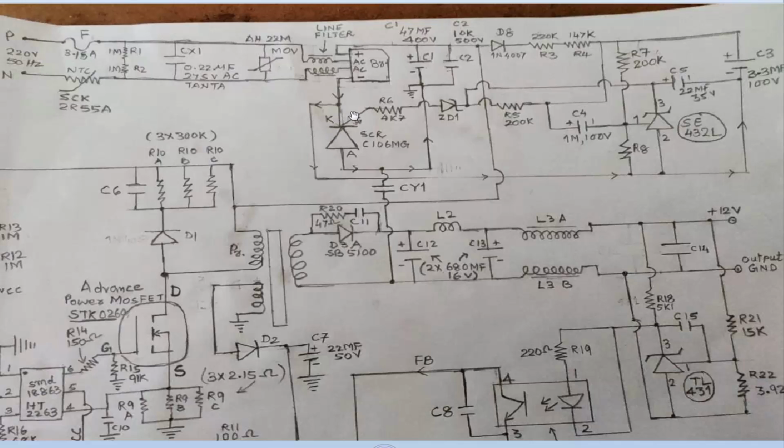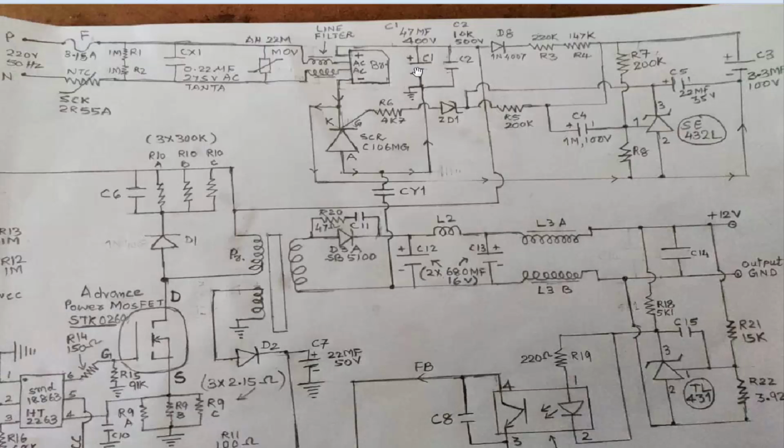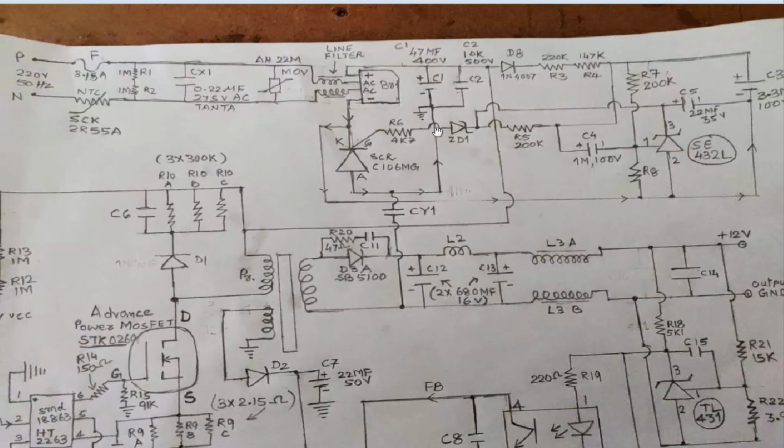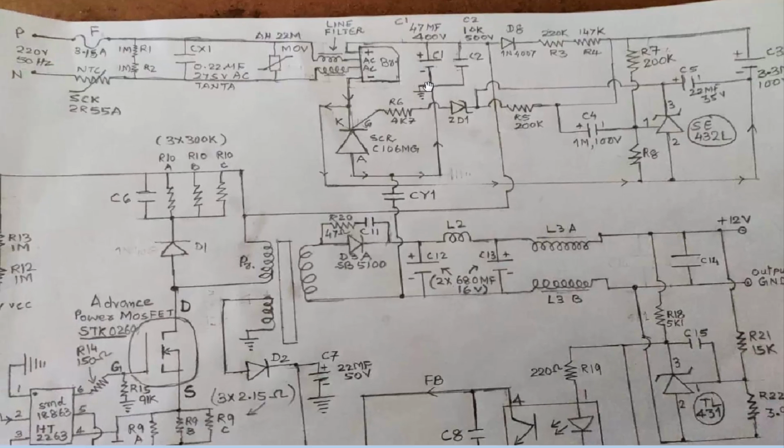So it will trigger, and when this circuit activates, the SCR will conduct, and the ground will pass to this capacitor, the main bulk capacitor. So this capacitor will receive the ground level. Before that it was receiving just positive voltage, and the ground line was disconnected through this SCR switch. It is working as an SCR switch. It is to ensure a specific voltage level.